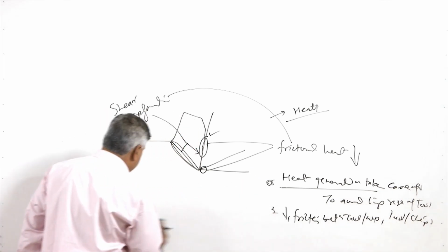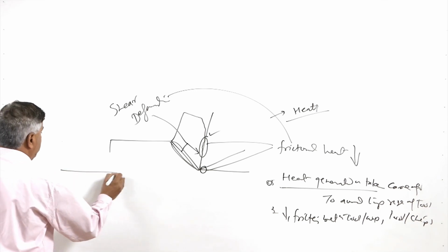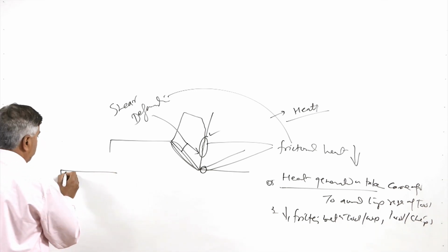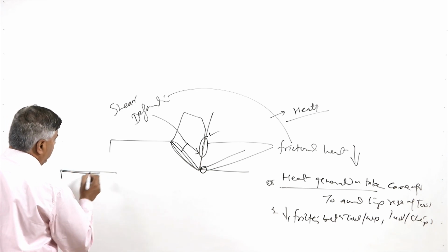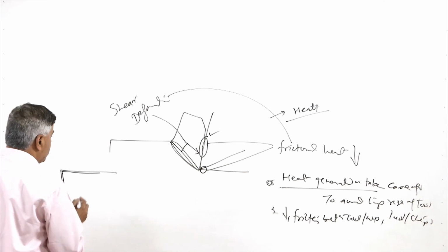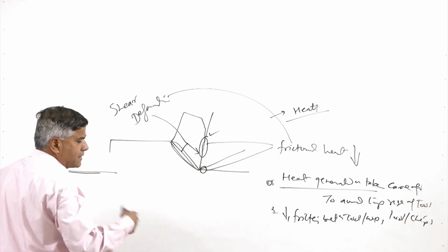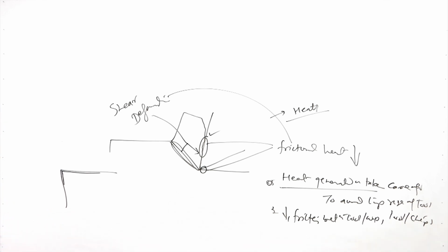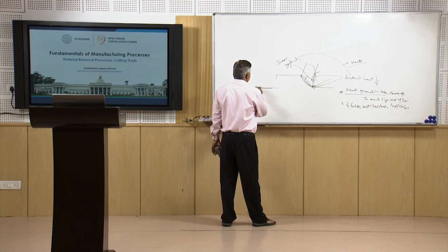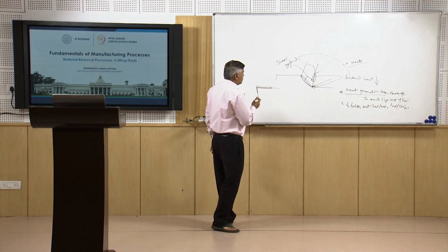In order to deal with these conditions, because both these conditions will lead to the loss of material from the tool, because the heat generation leads to the softening of the flank and the face as well as the nose. So, it leads to the loss of material by adhesion, abrasion, diffusion, chemical reaction as well as deformation. At the same time, rubbing of the chip with the tool also causes wear due to the friction.